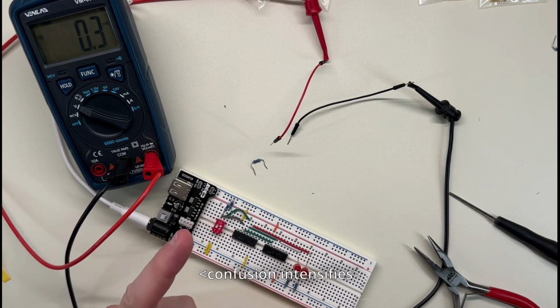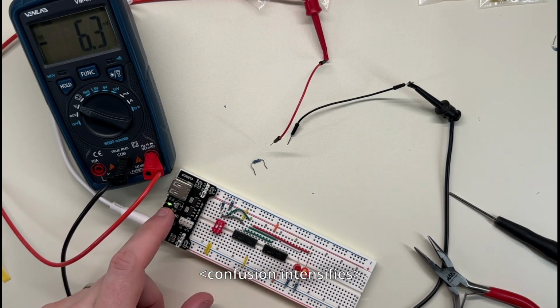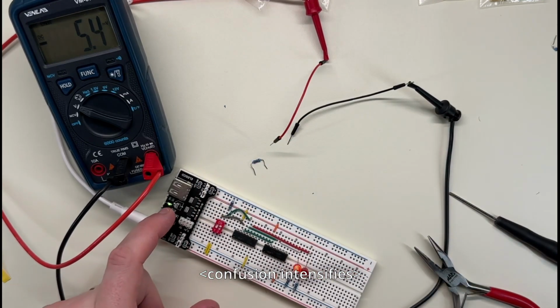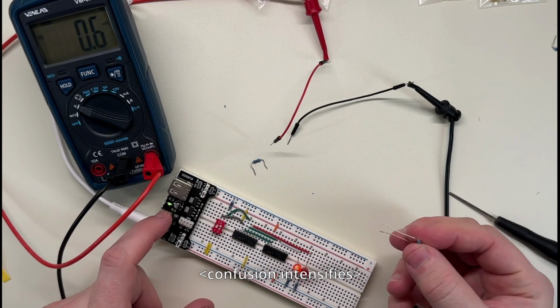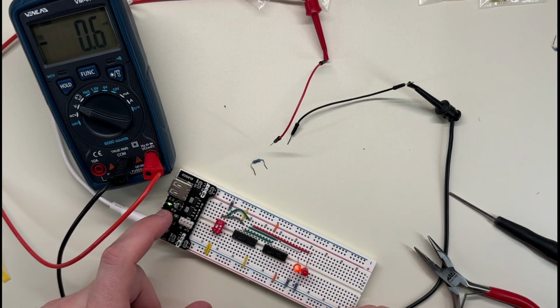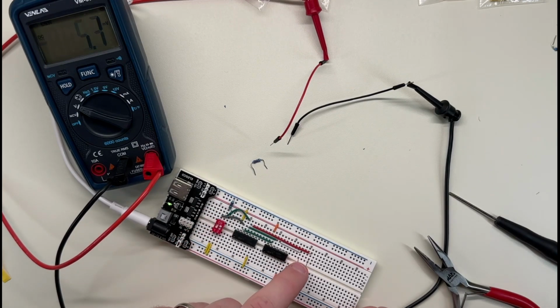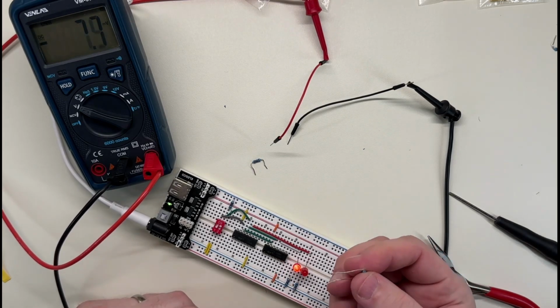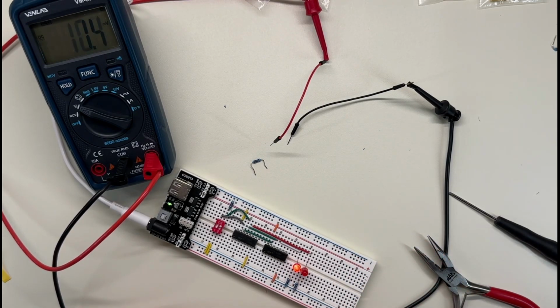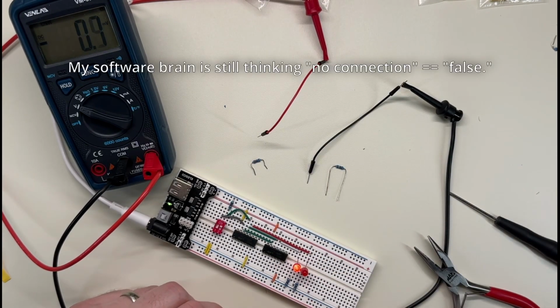Okay, I keep getting confused about this though, because there's a good chance that it's reading as very low anyway, because I mean that'd be kind of like not having this. Well, look at that though. When this is not connected at all, it's reading it as on. Because both of these have to be on for this LED to light up. That's the carry bit. So it's reading it as high. But it's not connected. Yeah, it's reading it as on, the same as if number 2 was on, but it's not on. So why is that high?